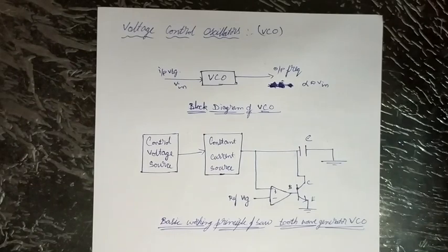The voltage is compared with the reference voltage using a comparator. When the capacitor voltage exceeds the reference voltage, the comparator generates a high logic output, which triggers the transistor, and the capacitor, which is connected to the ground, starts discharging. Thus, the output waveform is a representation of charging and discharging of a capacitor. The frequency is controlled by the input DC voltage.